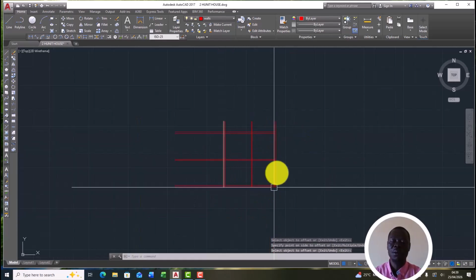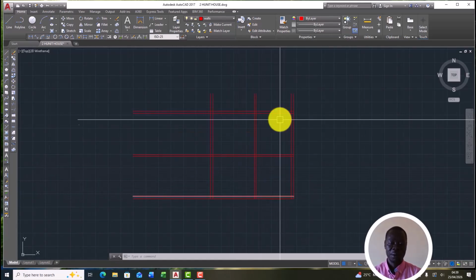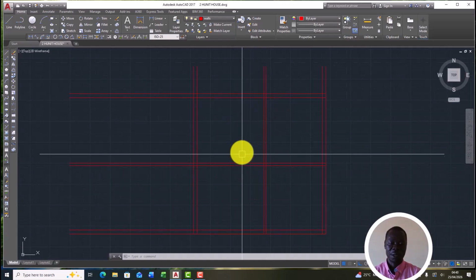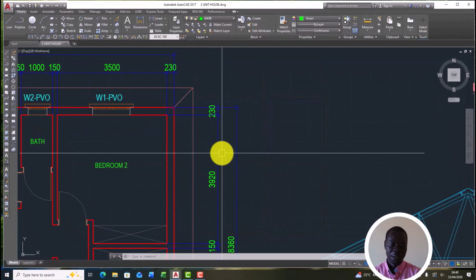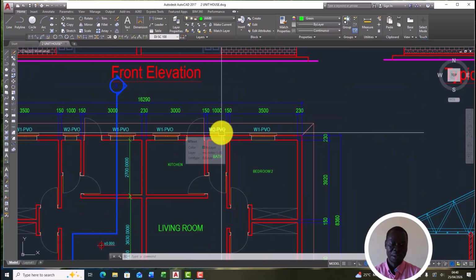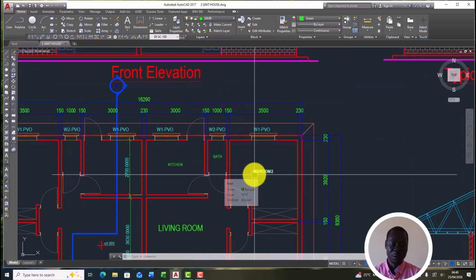And yeah, we are almost done with one side of the unit, but still there is this sitting room, this bedroom, there's a toilet here. We have to create that. So we go and look at the size of the toilet here, which is 1,000 millimeter. The normal size is 1.2, but for this case it's only 1,000 millimeter.